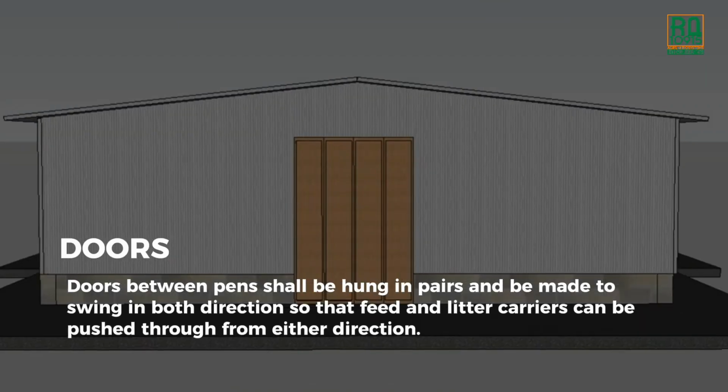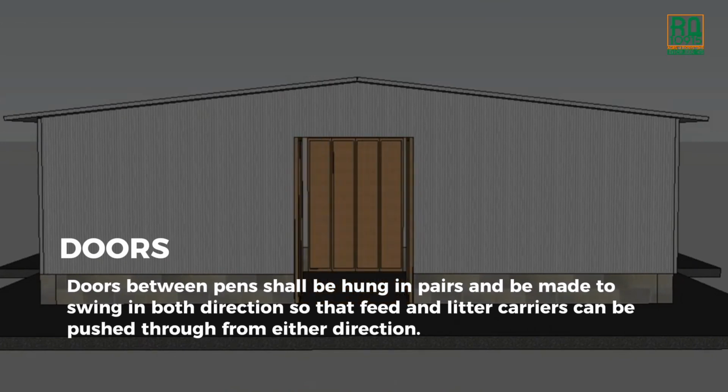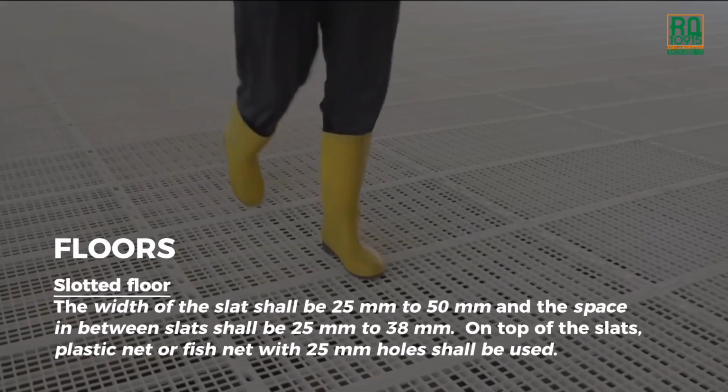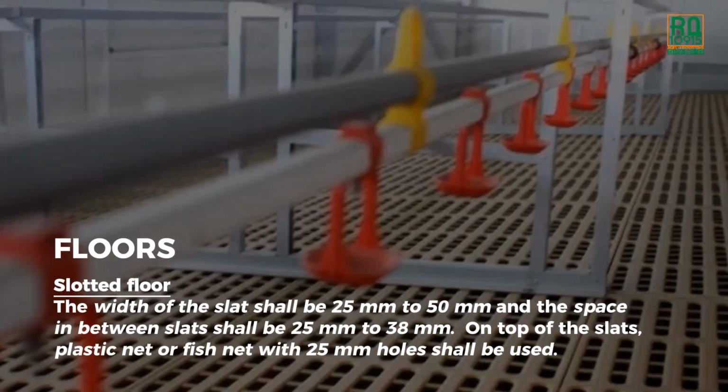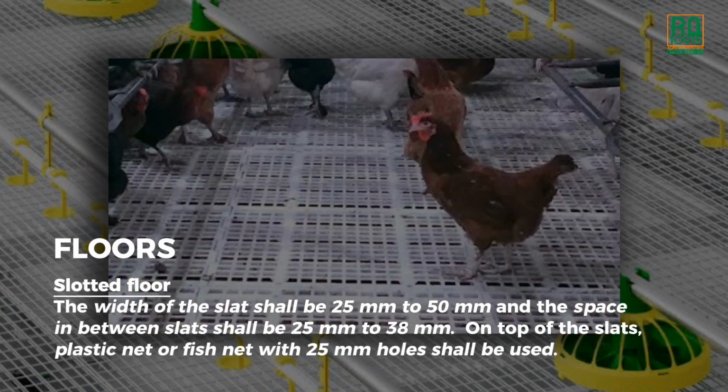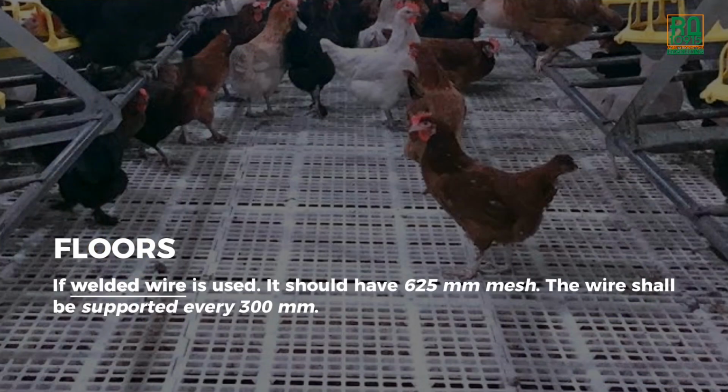Doors between pens shall be hung in pairs and be made to swing in both directions so that feed and litter carriers can be pushed through from either direction. Floors. Slotted floor. The width of the slat shall be 25 mm to 50 mm and the space in between slats shall be 25 mm to 38 mm. On top of the slats, plastic net or fish net with 25 mm holes shall be used. If welded wire is used, it should have 625 mm mesh. The wire shall be supported every 300 mm.